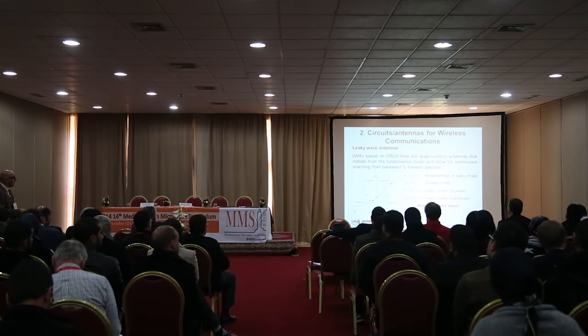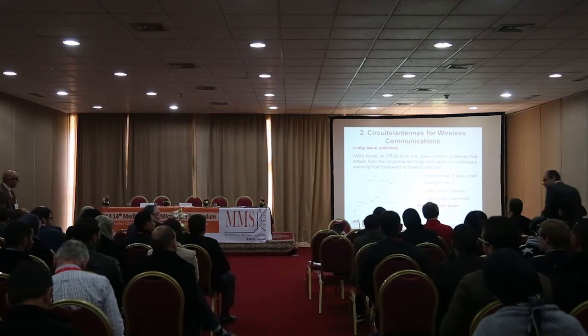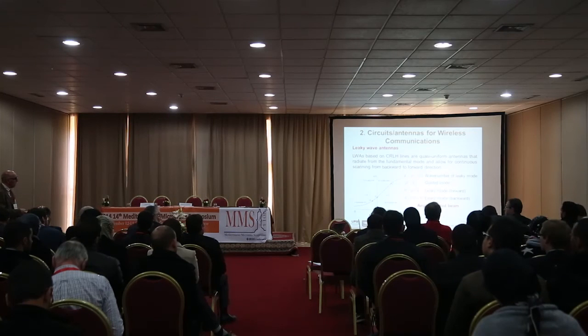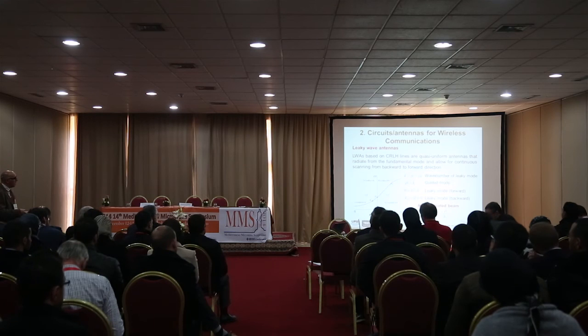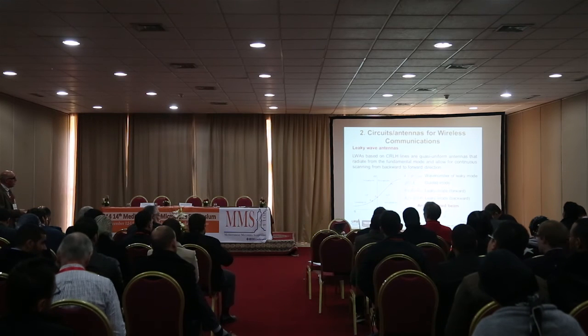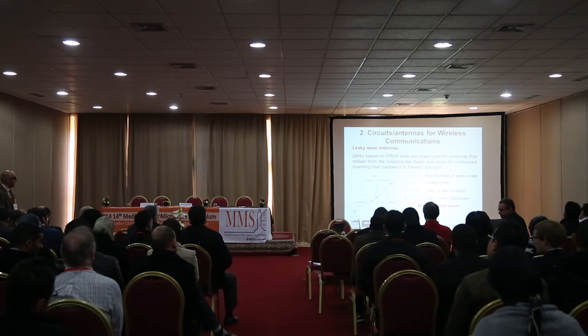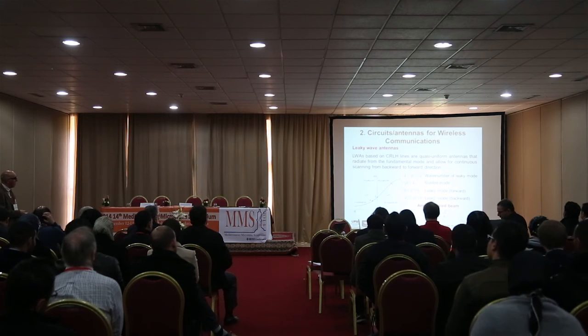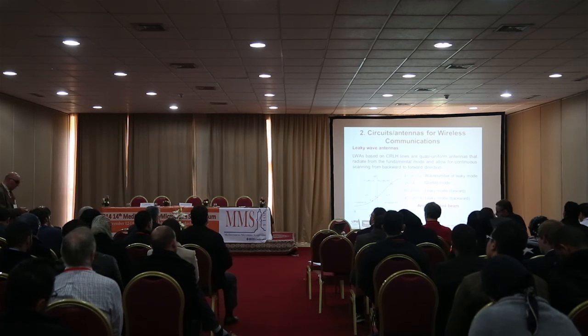We are in this region, which is forward. And if beta is negative, but the absolute value is smaller than the wave number in free space, then the mode is leaky, but it is backward. This corresponds to this region here. And this expression gives the angle of the radiated beam, from which it can be seen that here we have broadside radiation, forward and backward radiation.